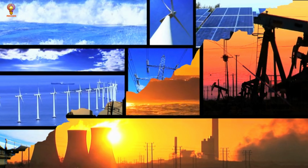Turbine and generator process. Steam rotates a turbine, which drives a generator to produce electricity. Cooling and recycling. After passing through the turbine, the steam is cooled, condensed, and recirculated. Cooling is often done using a cooling tower or direct water exchange with rivers. Radioactive waste management. Spent nuclear fuel is stored in cooling pools or dry casks for long-term disposal.